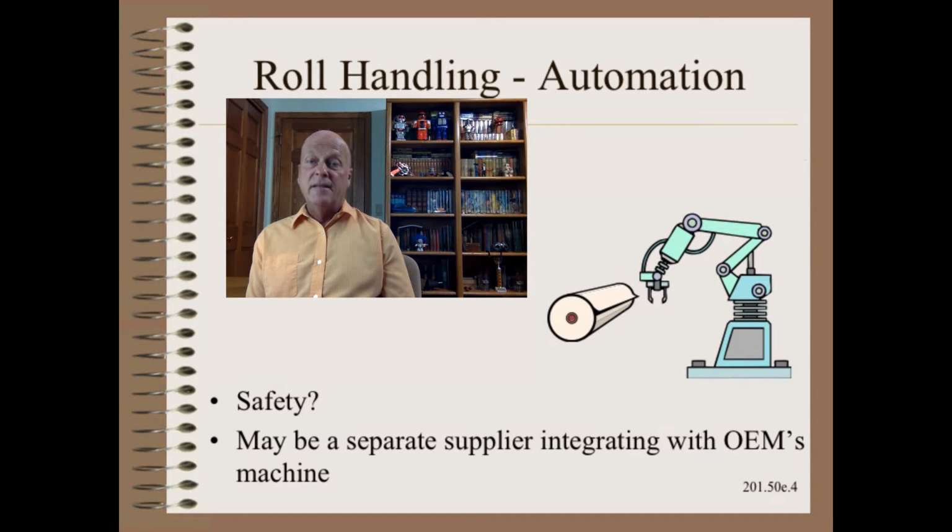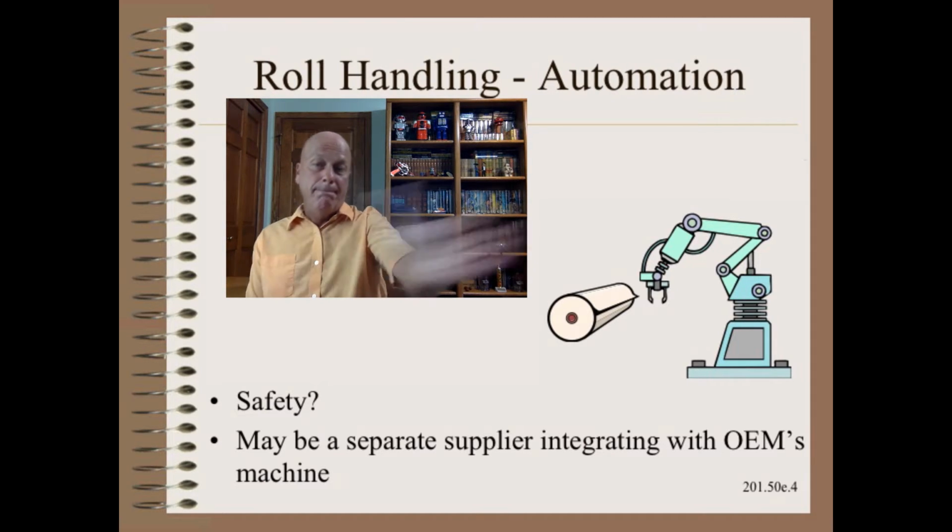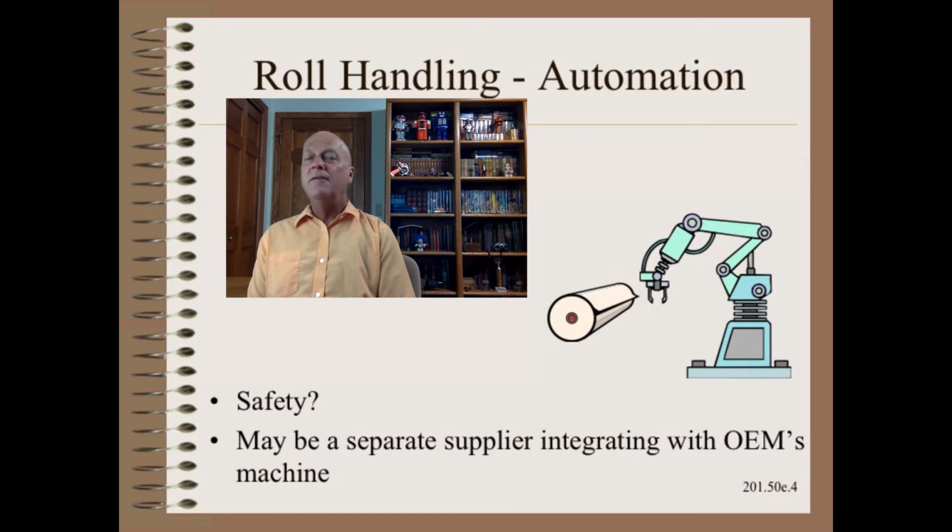The second area is safety. Automation makes sudden and unexpected movements. Light curtains, if not complete fencing of the area, is needed because, as they say, robots can have a very nasty backhand. This need for the highest levels of safety unfortunately makes fallbacks and maintenance even more challenging. Thus again returning to our need for higher levels of reliability than perhaps any other part of the plant. We covered MTBS, mean time between service, in the performance agreement section of our web machine buying guidebook.